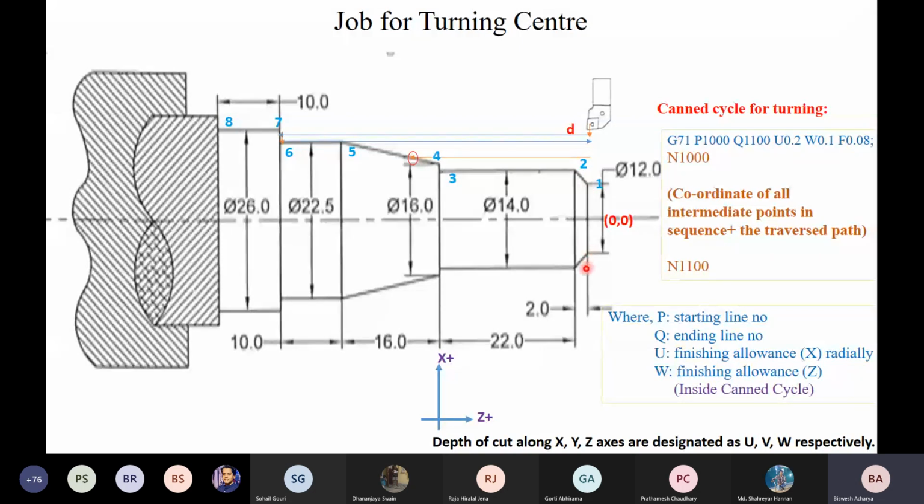So what is the difference between the roughing and finishing operation? In roughing operation I am more focused on removing the extra material without thinking of the surface finish. But once the dimension approaches the final dimensions, I may go for an operation like finishing, where I may change some of the parameters and machine in such a way that the final surface finish will be better.